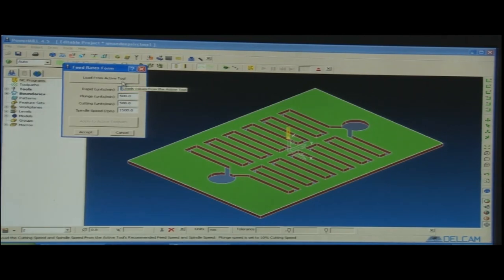Then okay, we can now select the feed rates. Now, load from active tool. Active tool means when the tool is actually working and the machining is happening, what is the load that the tool gives to the workpiece; those values can be put here. We skipped the plunge options before, because I will just fix that here. Now, how the tool enters the job for machining.